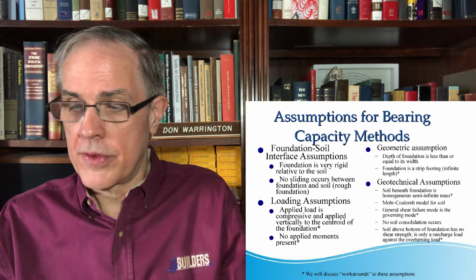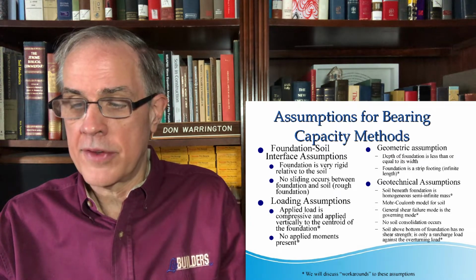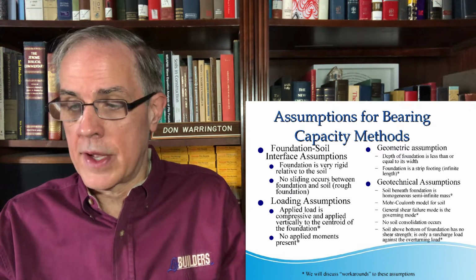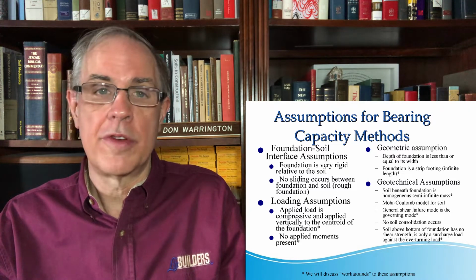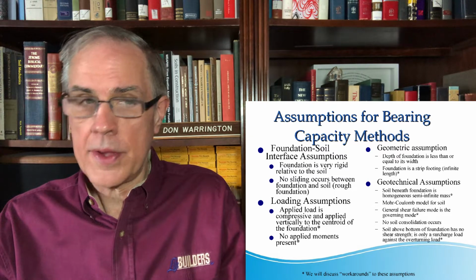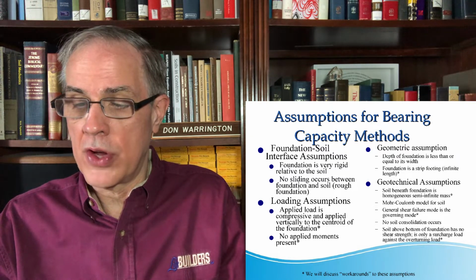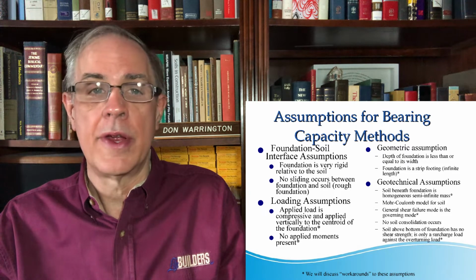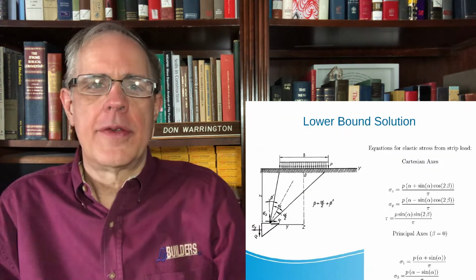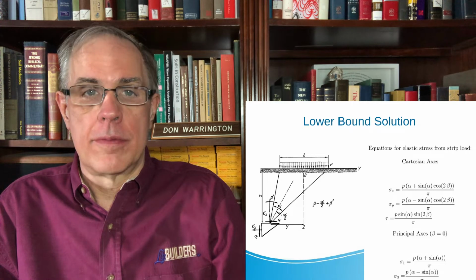The soil beneath the foundation is a homogeneous semi-infinite mass. The Mohr-Coulomb model applies, and the general shear mode is the governing failure mode. There's no soil consolidation, and the soil above the bottom of the foundation has no shear strength. There's only a surcharge load. Let's start with the lower bound solution.